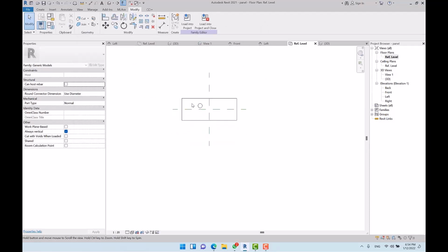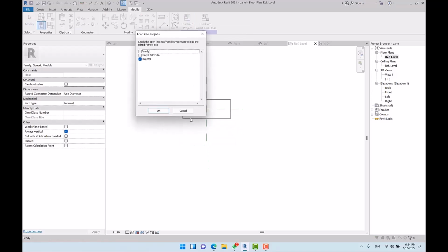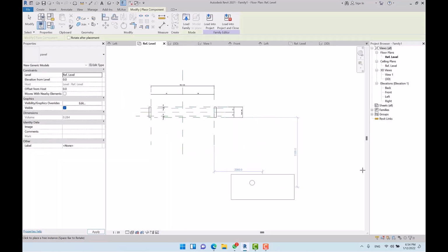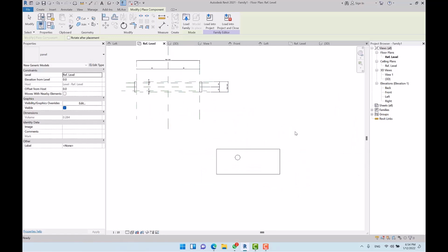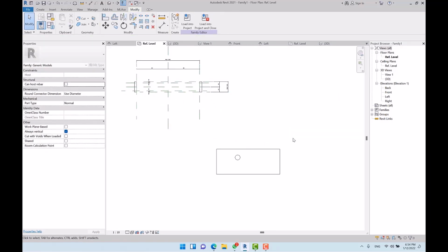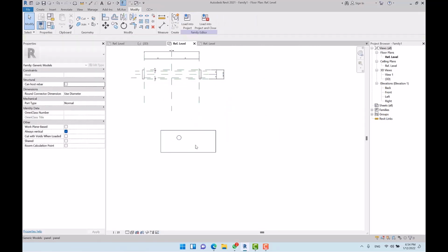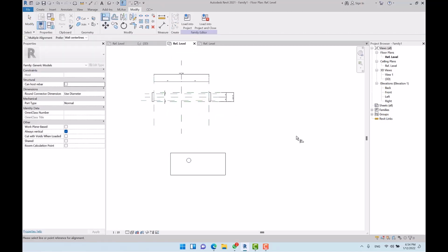panel, save, and then I load it into project, which is the another family template file, because this is considered as a nested family, gonna be used inside the another family, which is here. Check this out. Here there is a point that you should know, so watch this part carefully. Here when I load an object, the object is capable to be aligned with some of other objects, but from specific sides.